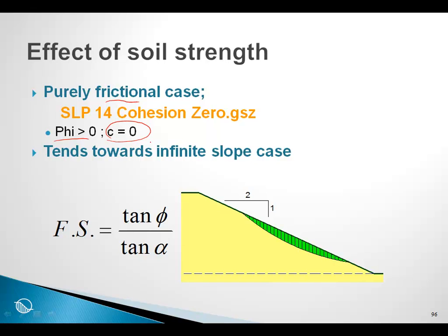And in this particular case, it turns out that when you have, for example, a grid and cohesion is 0, then the critical slip surface will be somewhere on the edge of the grid. And the tendency then is to move the grid. But once again, the critical is on the edge of the grid. And then we move the grid, and the critical again is on the edge of the grid.